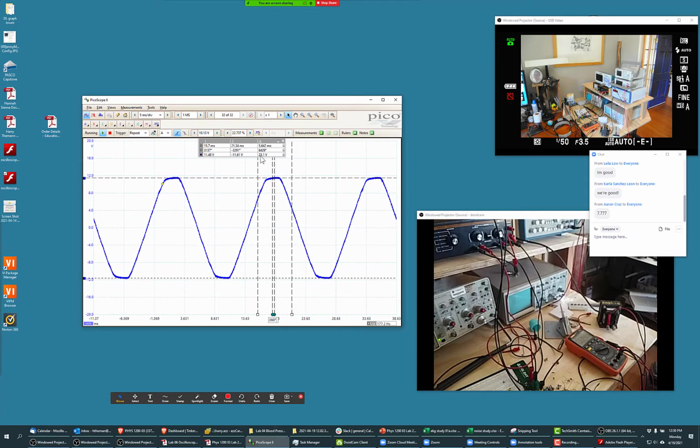Yeah. So if you see now what you calculate now for the RMS is much closer to the 8.38. And my guess is that the discrepancy is because this is not a good sine wave, not a perfect sine wave. So that fools the voltmeter.